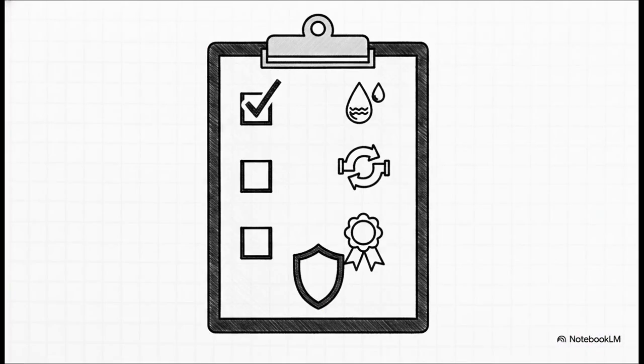Finally, step 6, the final system check. This is where the rubber meets the road. This is where we ensure all the theoretical math and the real-world factors align perfectly. Before you spend a single dime on equipment, treat this final phase as an absolutely non-negotiable checklist. Does the system actually meet the required flow and volume at your peak temperature rise? Does it recover to the set point between those peak draws? Have you explicitly included distribution and recirculation losses? And does it respect local codes and manufacturer performance curves? Walking through this checklist mechanically protects your facility from rapid short cycling and endless lukewarm water complaints.